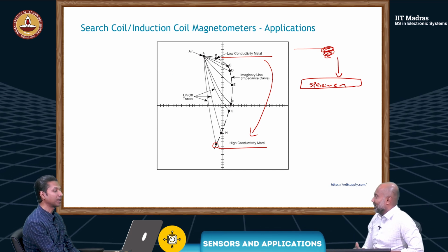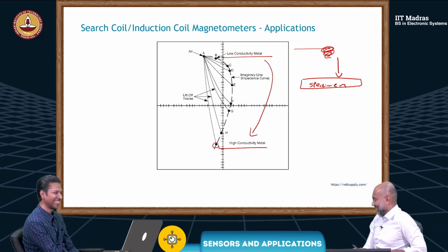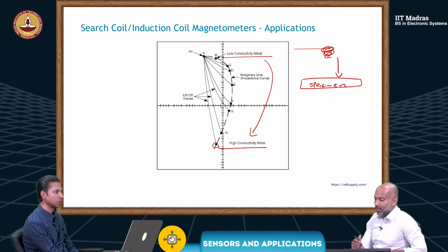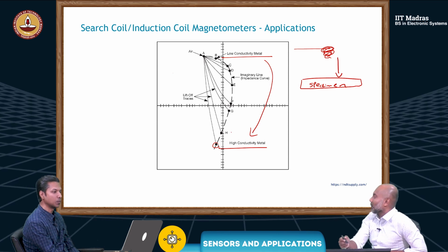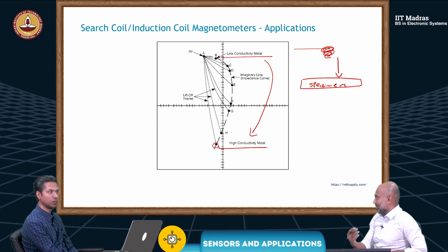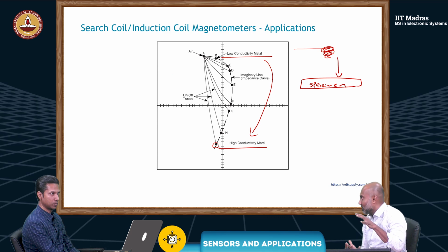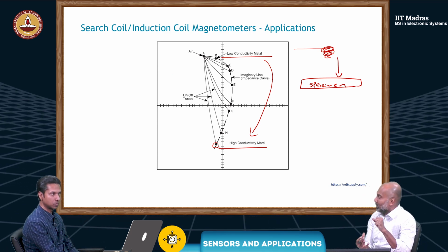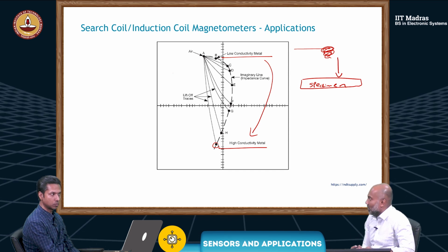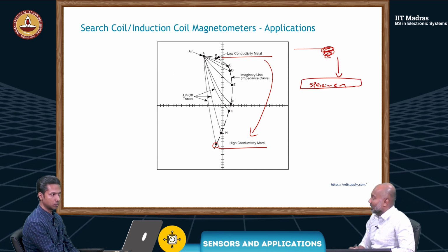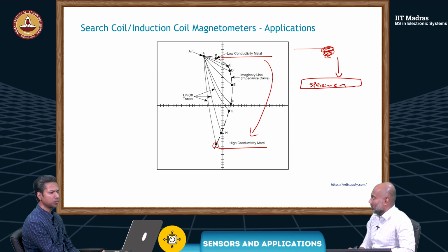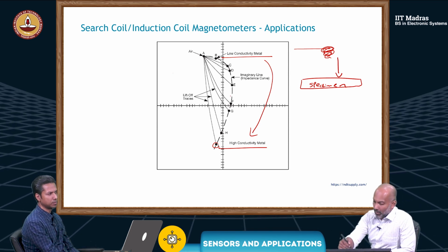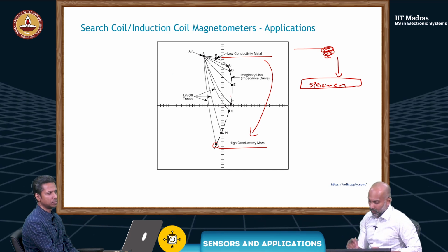I was thinking about the real part alone. Yeah. So generally the liftoff traces will increase with high conductivity. The higher the conductivity, the higher the liftoff is, because initially we're nulling the instrument, right? So from that null point to the actual measurement also depends on the conductivity. If conductivity is more, change will be more. Which is basically what you're seeing there, yes.